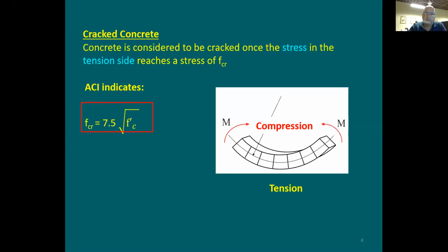So at the beginning, you just have the self weight, and then you start to add some loads to it. Now the stress is going to be growing. It's going to start as a very low value, lower than this. And as you add more loads to it, the stress is going to be growing, at the bottom and the top, and they're going to be the same in a rectangular section. Tension, compression, they're going to be equal as long as you are within the cracking limit. Once you hit the cracking stress at the bottom, what's going to happen now?